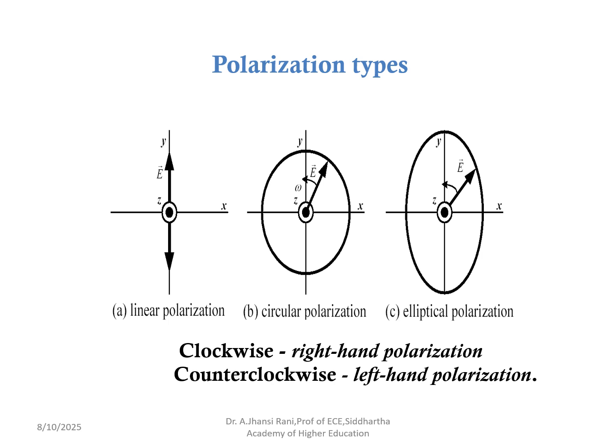Now circular polarization. If the wave is propagating in the z direction, for circular polarization you have two fields, x and y. These two fields are orthogonal to each other. They have the same magnitude, and the phase difference between them is 90 degrees. As time progresses, the tip of the electric field is tracing a circle.